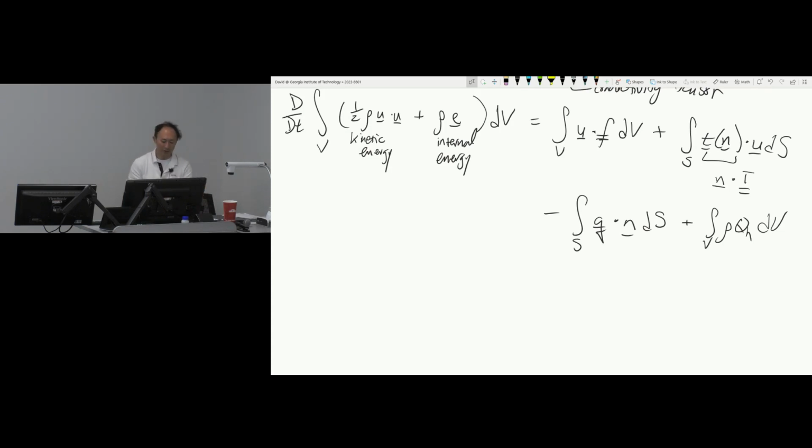So what we're going to do is separate this into two separate equations. One's called the mechanical energy equation, which is what we're going to use if you don't have any heating elements. And one's a thermal energy equation. We're going to do that by looking at the Cauchy momentum tensor, dotting with velocity, and integrating that to get the mechanical energy equation. We're going to subtract it from this thing.